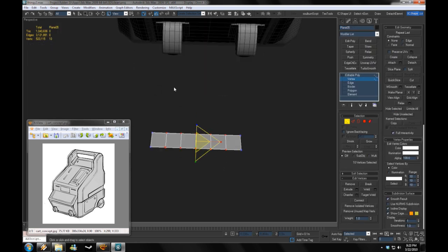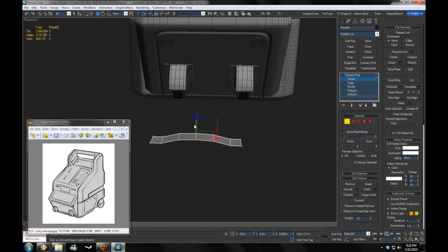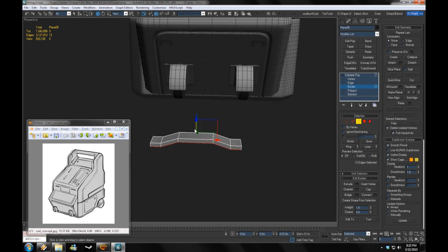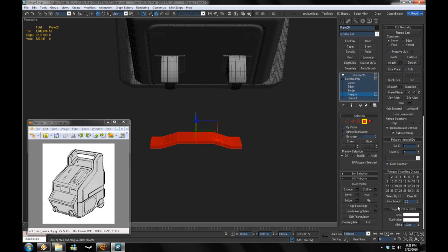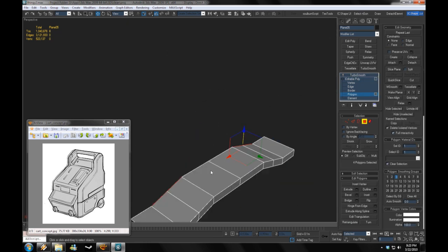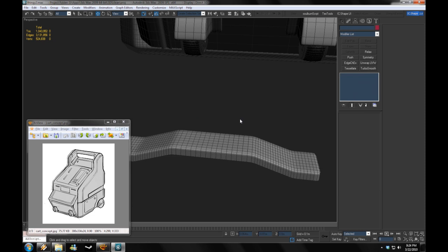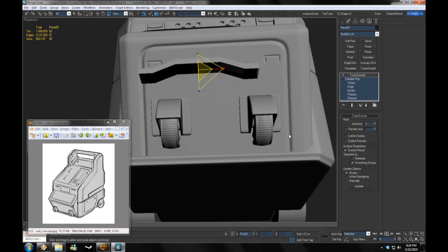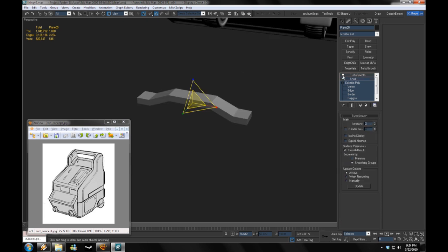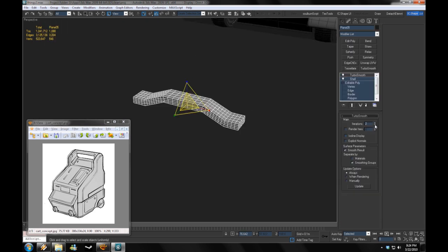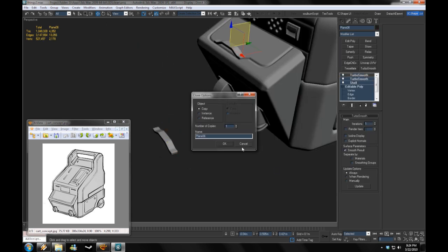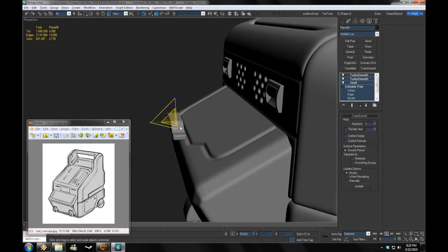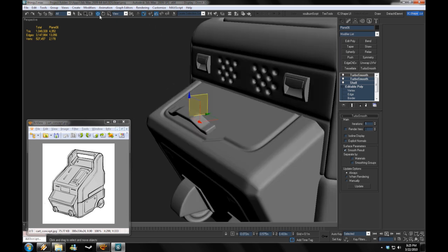So now I'm going to make another, more industrial handle for this kind of waste bin on the front. And I'm just going to be using double smooth, as usual, because it's simple. I'm sure there's a proper name for that technique, but I don't know it, so I'm not going to bother. And I've used shell to give it some quick thickness, instead of just using extrude face, or similar. And I'm going to place it.